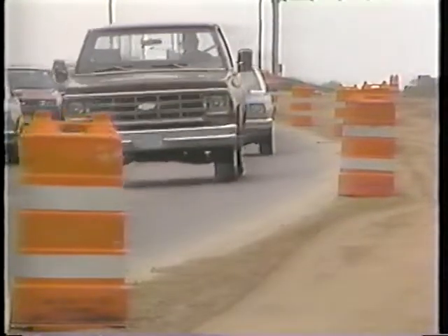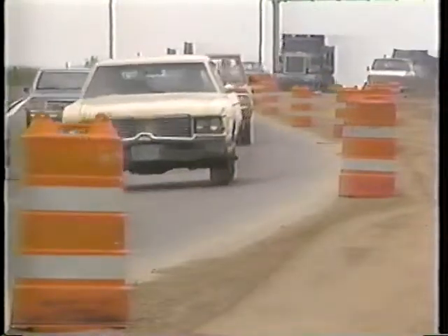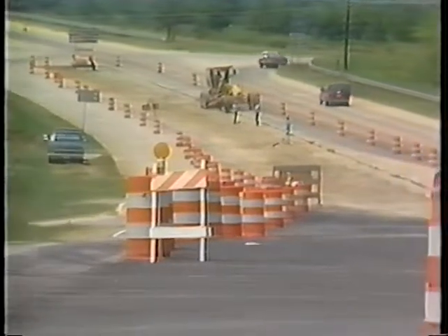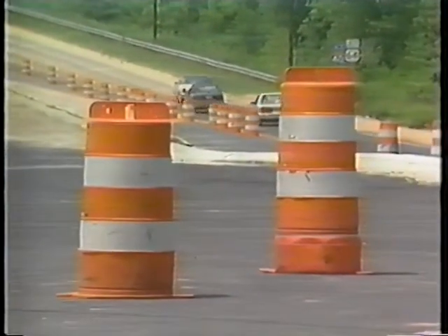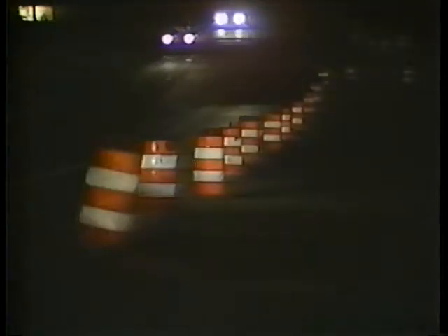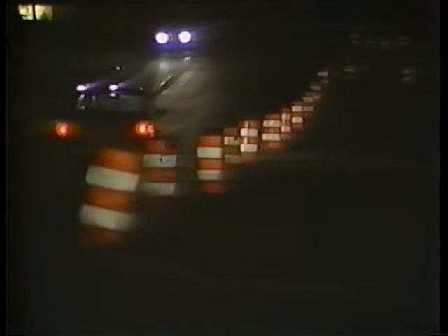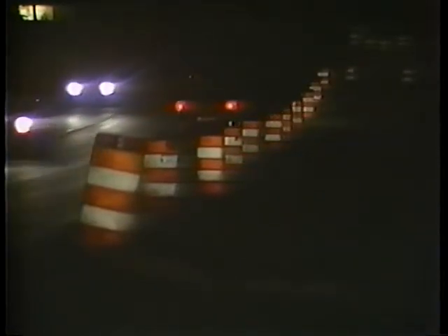Drums are used as either channelizing or warning devices. They are highly visible, give the appearance of being formidable objects, and therefore command the respect of drivers. Plastic, not metal drums, shall be used. The Manual on Uniform Traffic Control Devices requires that markings on a drum be horizontal orange and white stripes that are retroreflectorized 4 to 6 inches wide.